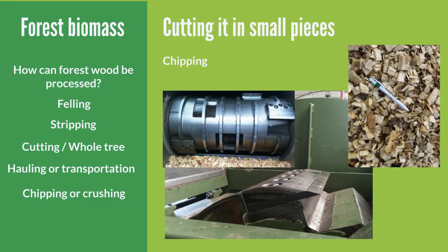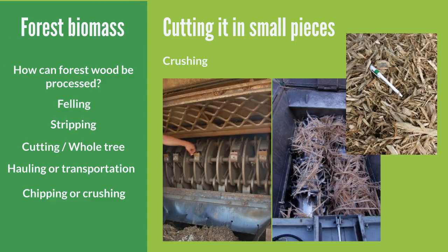Chipping uses blades and counter blades to make a clean and polished cut. However, impurities or debris like dirt and stones can quickly ruin the sharpness of the blades. Therefore, it can be used only for impurity-free plants. Crushing, on the other hand, is suitable for dirty material, but produces a biomass with a thicker and irregular size.